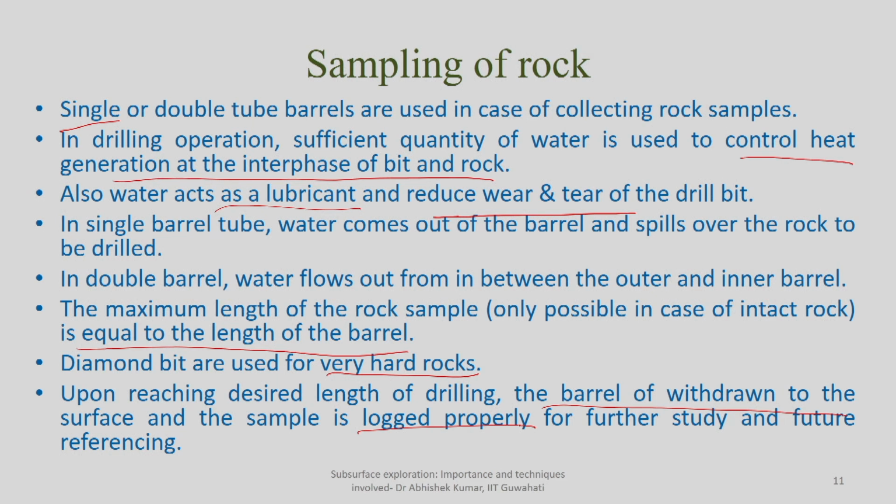So what I mean to say here is, whenever you withdraw the barrel onto the surface, because of the cracks available in its natural condition, or because they were created by the drilling operation, the entire core will not come. So that's why you have to lower the barrel again and again and bring it onto the surface, and then finally you will log it properly. Whatever sample you are collecting, you will store it properly: what depth you had collected, what was the borehole number, what was the depth from which it was collected, and what time it was collected.